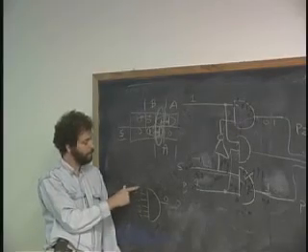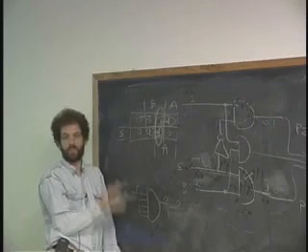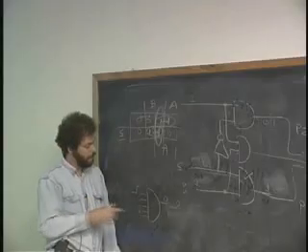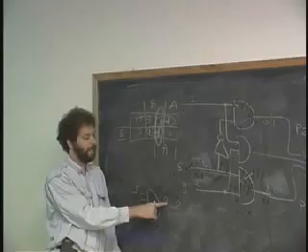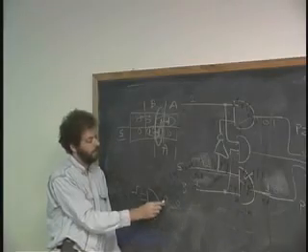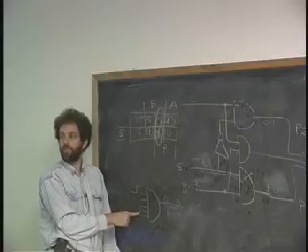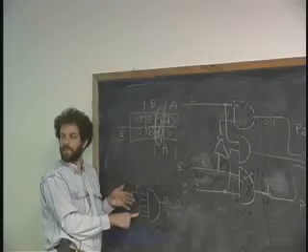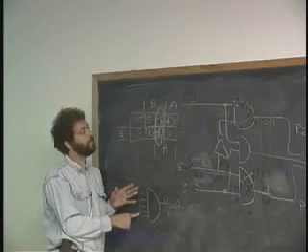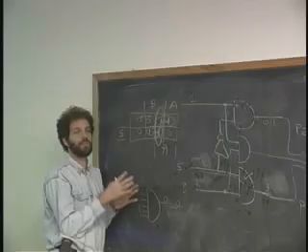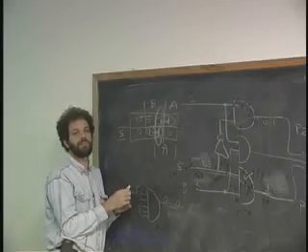Because here, this one's a 1 and this one's a 0. It's the only one that changed. The rest are constant, because that's the conditions under which we're operating. At least one of them was held at a 0 and did not change. So did this output actually change between these two states, or did it guaranteed stay low? If I have an AND gate and I hold one of the inputs low all the time, these things can wiggle up and down for all they want. Nothing's going to happen. So as strange as it may sound, a sum of products implementation can never generate a 0 to 0 hazard. Okay?